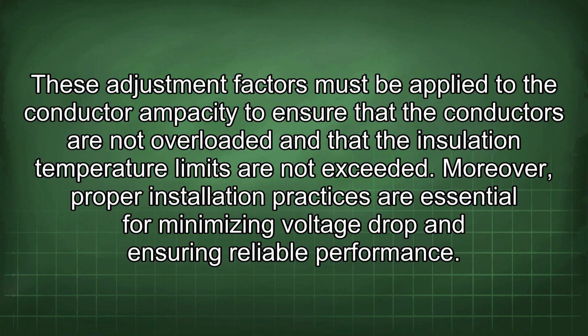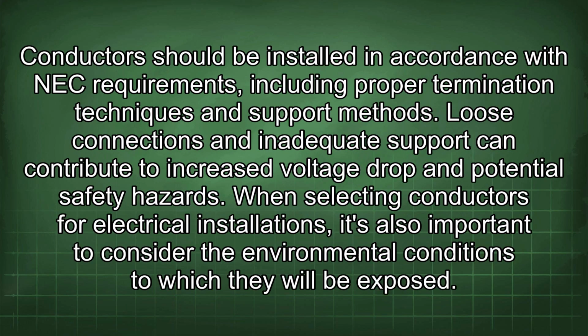These adjustment factors must be applied to the conductor ampacity to ensure that the conductors are not overloaded and that the insulation temperature limits are not exceeded. Moreover, proper installation practices are essential for minimizing voltage drop and ensuring reliable performance. Conductors should be installed in accordance with NEC requirements, including proper termination techniques and support methods.